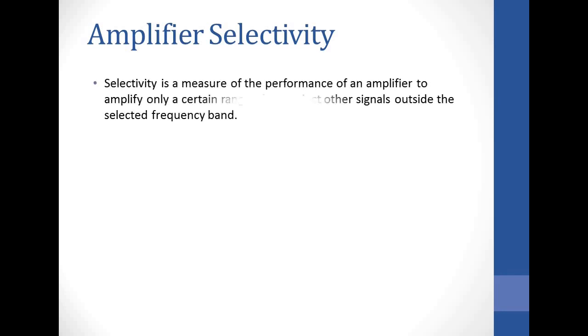Another important term that we want to look at is selectivity. Selectivity comes from the word select. We want to select a particular range of frequencies to amplify. So, therefore, we say an amplifier that has got selectivity is an amplifier that can only amplify a certain range of frequencies, whilst anything outside that range is not amplified.